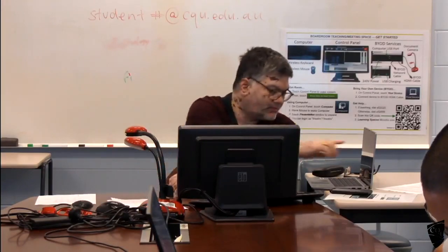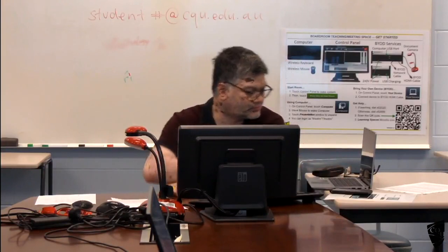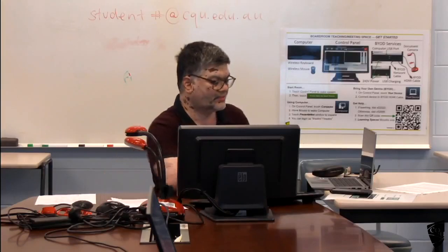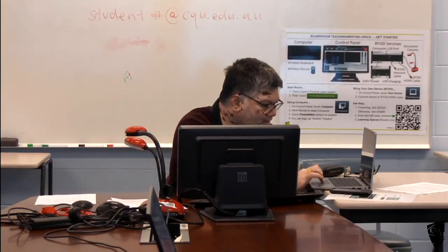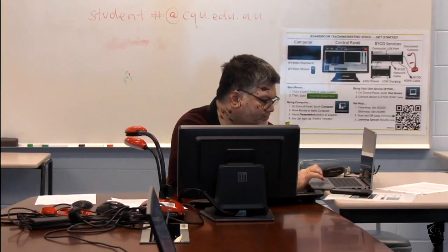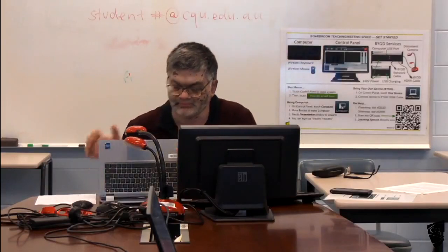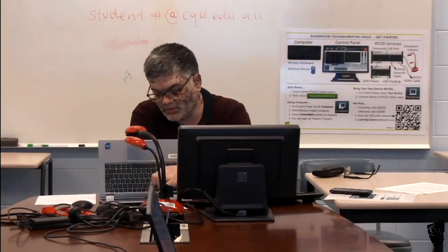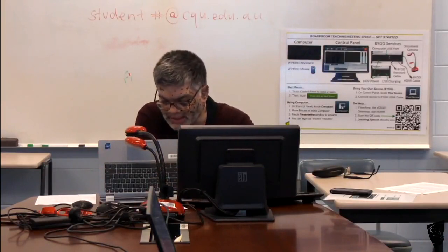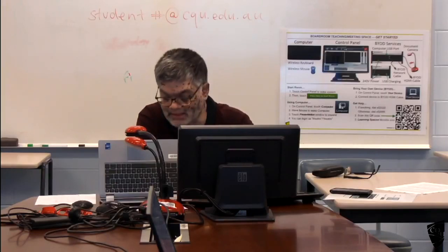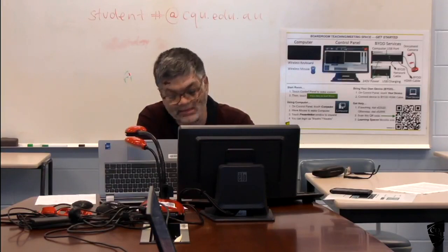So now we need to find out for the interior spans. For interior spans, it is the next table, 6.10.4.3b. So here they don't worry about the flat system. Everything negative moment is 0.65, positive is 0.35. Okay, for everything, for interior span, negative moment means at support, mid span is 0.35.